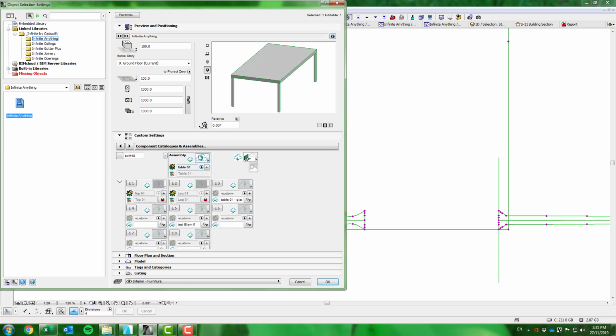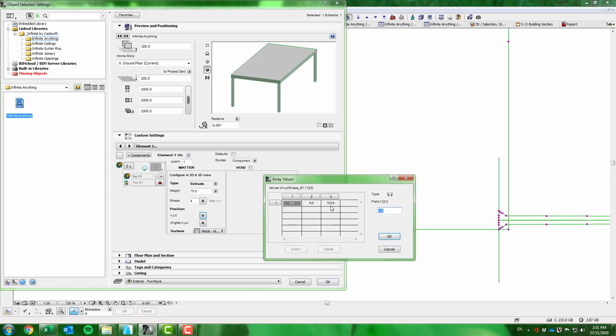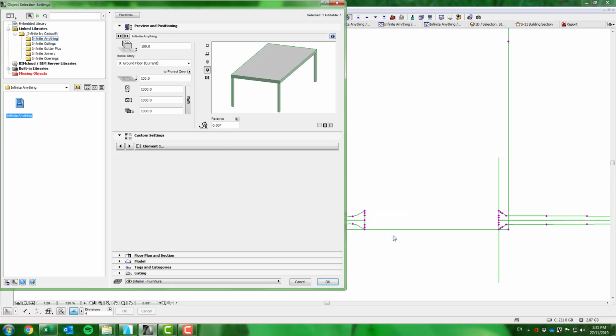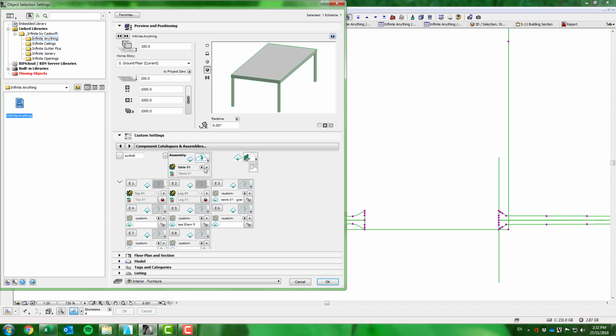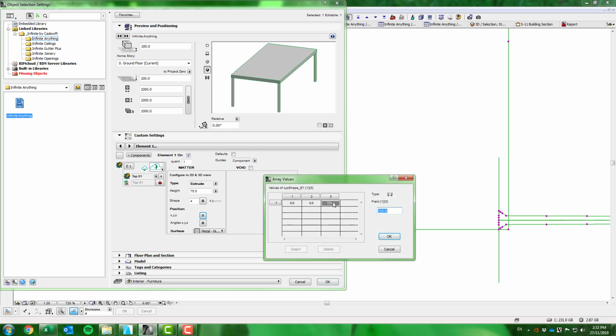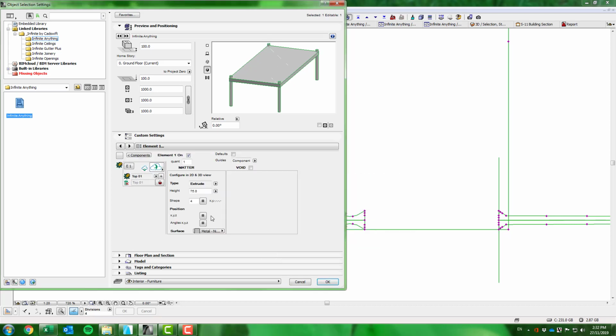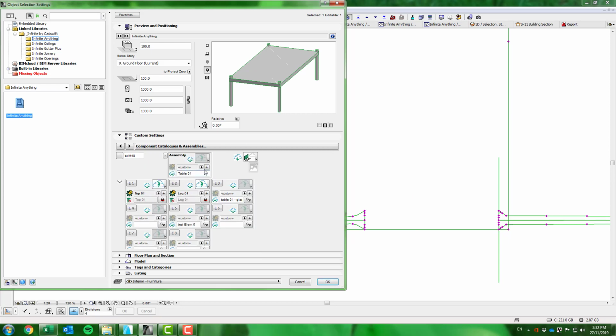So that when you save the assembly, it locks these 2 elements, but it also sets the positioning. So in this here before, I now can't edit the position of these elements. If I try change that to 600, click OK, it reverts back. But that's not due to this element, that's due to the assembly being locked. So if I uncheck that and I go back to that element and I want to change the top, 600, okay, so I can change it. But then if I go back here and I lock this back to table 01, it jumps back up to the 725. Okay, so that's the first table done.